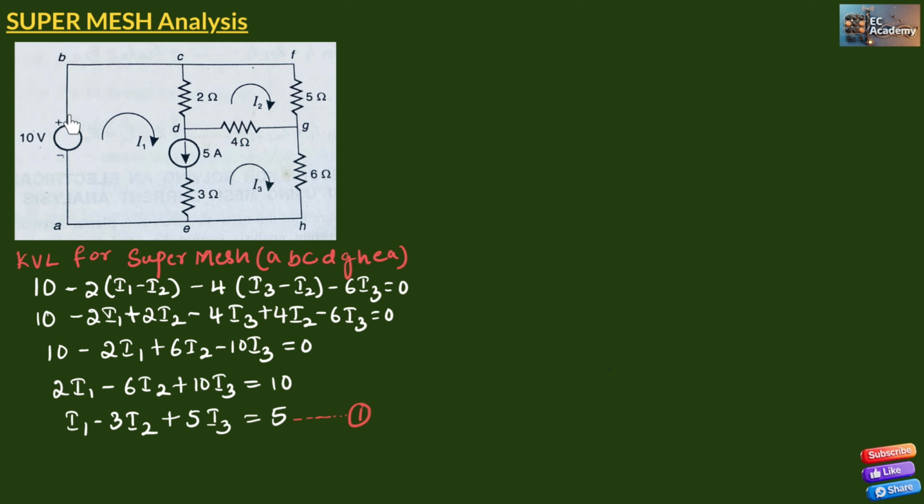Now once we apply KVL to the supermesh, there is one more mesh that is left out. So we can apply KVL to this loop or mesh. Let us apply KVL on mesh 2, which is C, F, G, D. The voltage drop across the 2 ohm resistor will be minus 2 into (I2 minus I1).